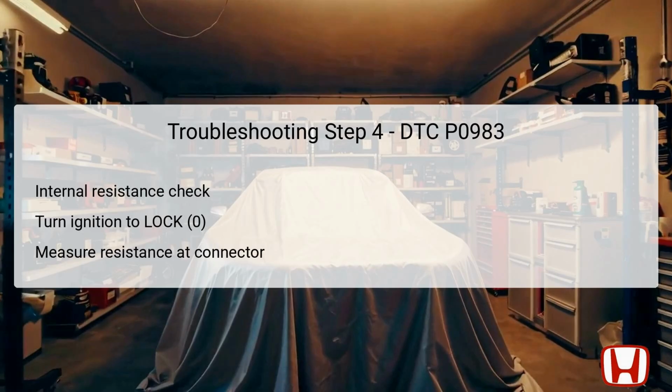Begin by ensuring that the ignition switch is in the lock position, ensuring safety during the procedure. Utilize the HDS to jump the SCS line, which helps to facilitate the testing process. Disconnect the PCM connector C49P, as you'll need to measure the resistance across specific test points.